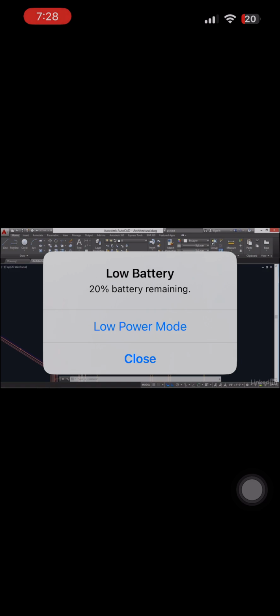In other situations, you might want to move objects relative to others, and you can use Object Snap to make sure that you're precise. So let's move this chair. I'll click it, right click to exit from the Select Objects mode. And this time, the base point matters. It matters exactly where that is. So I want to pick this midpoint here. So to do that, I'm going to hold down the Shift key and right click. That allows me to have access to this handy Object Snap menu. I'll choose midpoint.